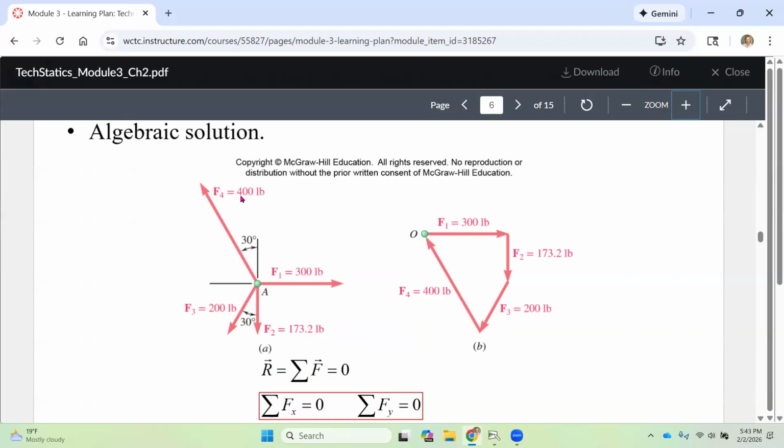But when I am adding and applying, as we're going to find out in just a bit, the equations of equilibrium, we can do that in our traditional concurrent force system where everything's coming from an origin. And then we're going to use the rectangular component method to solve these. The reason we do that is because the two main equations that we're going to be using for equilibrium are the sum of the forces in the x equals 0, you see that down here, and the sum of the forces in the y equals 0.